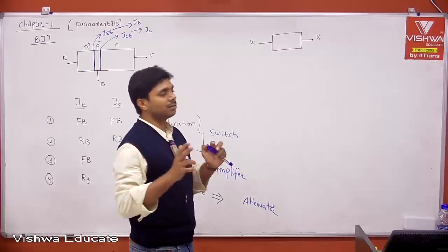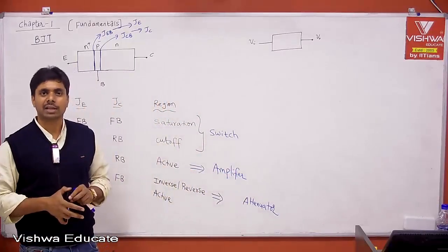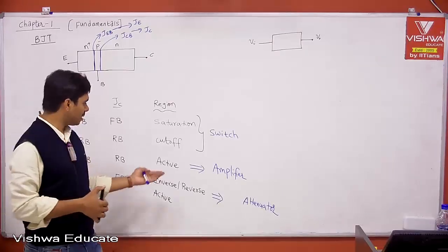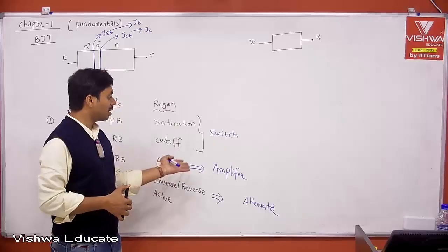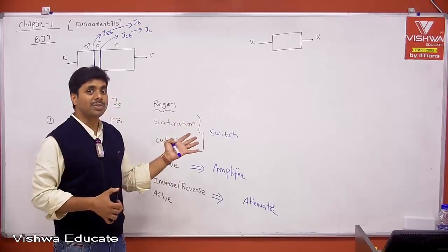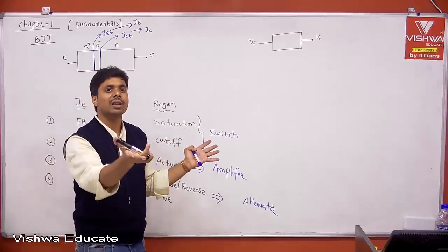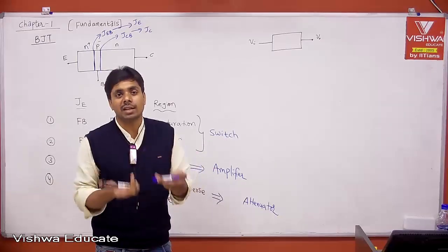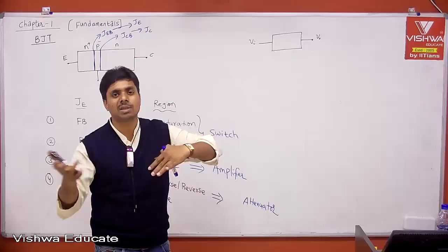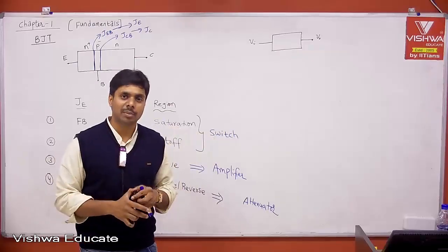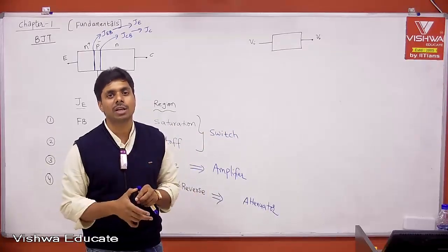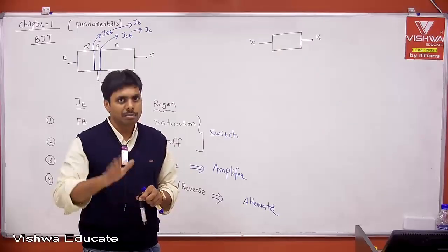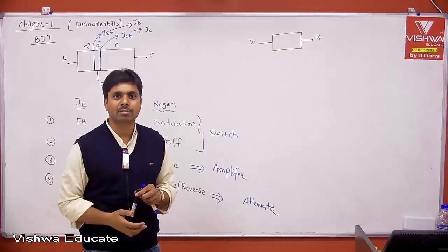Then using passive elements, can we get amplification? There itself is the answer. Using active elements, using a transistor kept in the active region, we get amplification because the BJT helps you get amplification. Internally it is not giving any energy, but it converts the energy from the DC power supply to AC power. That's why people call it an active element, because it is processing and delivering to the outside world. But that processing you cannot get using passive elements, okay? But anyway, I'll clarify that, just give me some time.